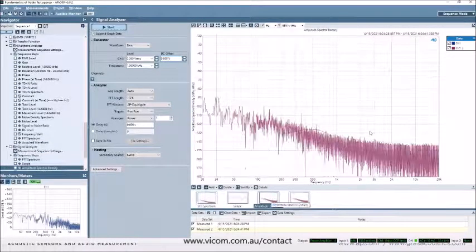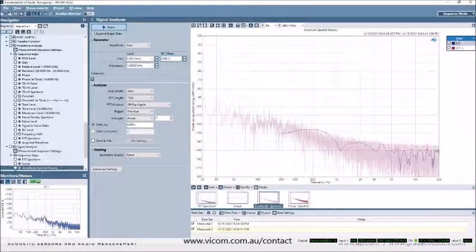If I'm measuring noise, and here it's a little bit hard to see, and I use amplitude spectral density, you'll notice that they're about the same amplitude, regardless of the length. The quick and dirty is this: if you're measuring coherent signals, or you want to extract the level amplitude of coherent signals, use RMS scaled FFTs.